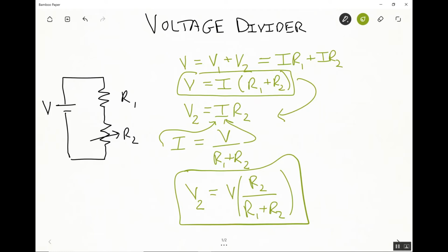All right, so what we have is that the amount of voltage that is utilized by resistor 2, and again, in this case, it's a photoresistor, is a function of the total voltage being supplied to the circuit, which is a constant, 5 volts if it's an Arduino Uno digital input-output pin. It's a function of that and R1, but then also R2.